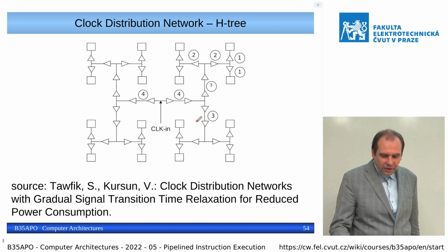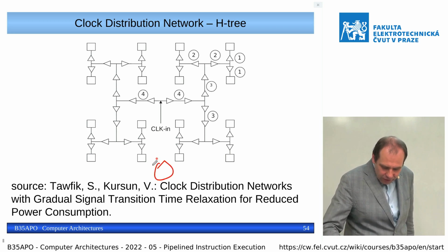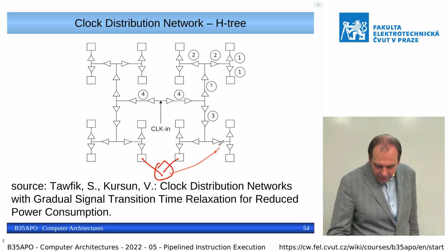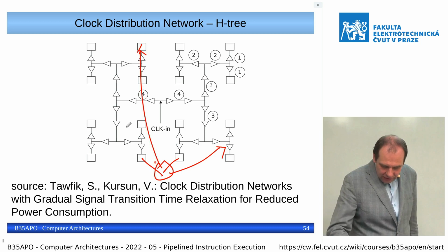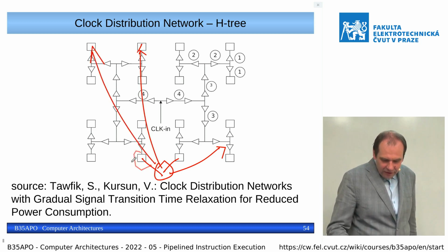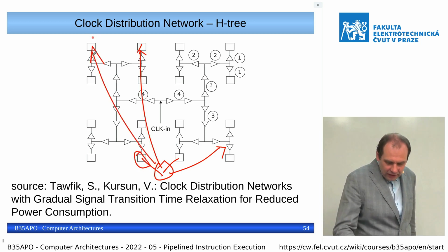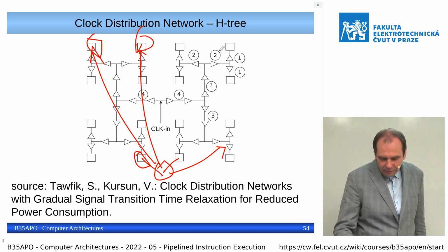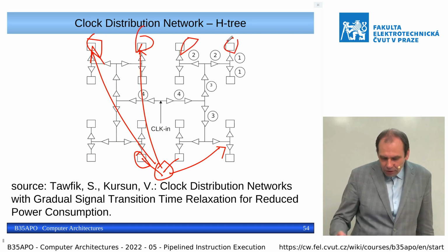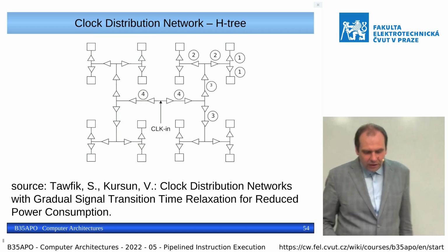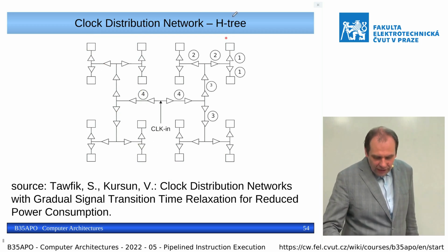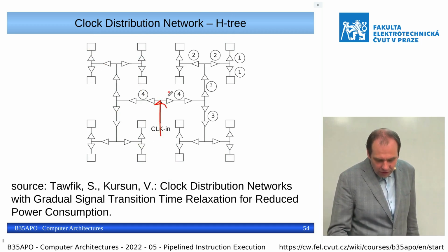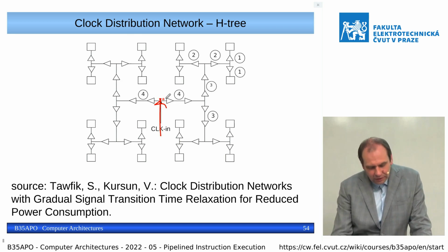And in the FPGA, or even in a complex design, it is done such a way that if we drive individual circuits directly from the clock input, then some will be clocked in advance, and the further ones are clocked too late. So we can do a so-called H-tree, where we connect the clock somewhere to the middle of the chip.